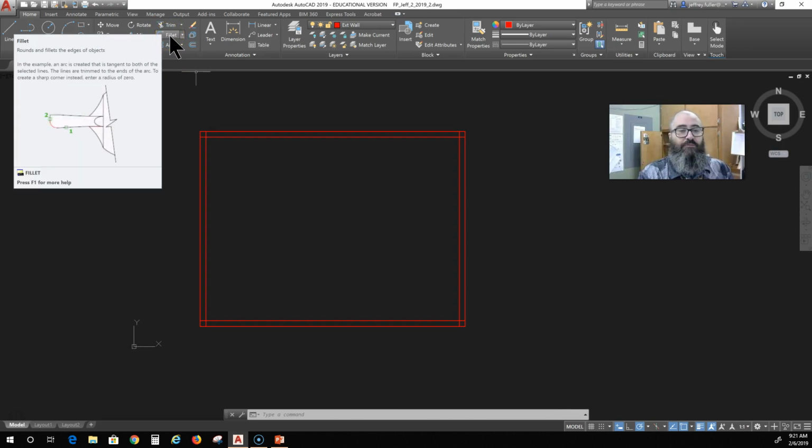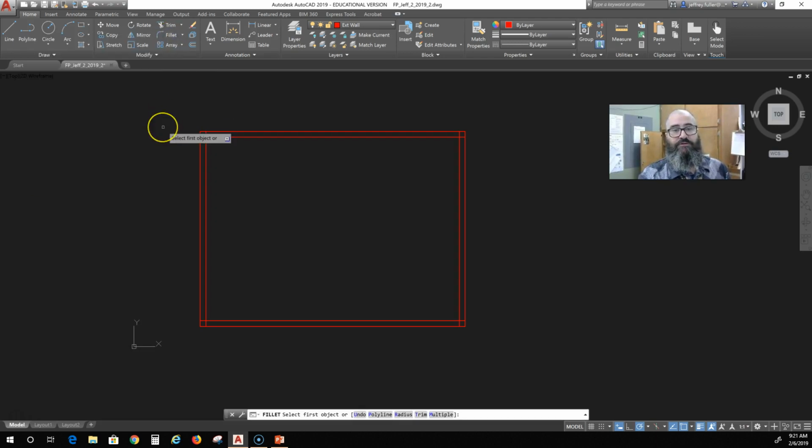Now a fillet is basically a round corner, as you see in this drawing that pops up as a little tutorial, and you can see the other side of that part has a completely square corner. That's what the side that is now round looked like before they filleted it. For filleting, you would click where it says 0.1 and then click where it says 0.2, and it makes a radius corner. However, if you just click on the fillet button without typing in a radius, it is automatically set for 90 degrees. Which isn't really a fillet, but it makes your corners for you.